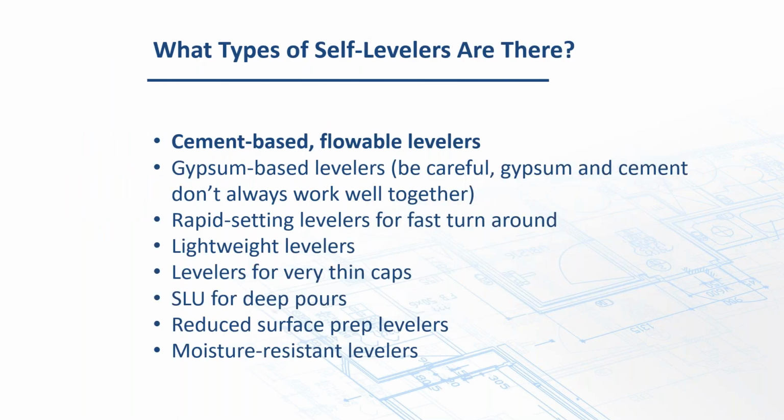Some of the different types of levelers out there: there's cement-based, flowable levelers. There are gypsum-based ones as well. Now be careful what you're doing with gypsum if you don't understand it well. Cement and gypsum do not play well together. Typically you build ettringite and can create bond breaks and so on. So gypsum's not as common on our side of the business because most of our adhesives are cementitious, but they're out there.